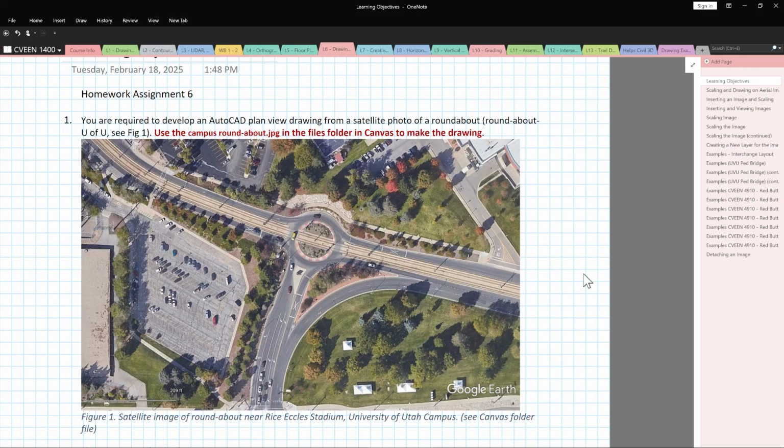The important thing to realize about these types of photos is they are called orthophotos, or orthographic photos, and what that means is the photo has been rectified so that it is perfectly flat. Normally when you would fly and take images with a satellite camera, the edges would be distorted, making it so that the distances would not be correct on top of the photo. But the Google images have been corrected to orthophotos, so we can use them to draw directly on and get approximate distances. So the layout we're going to do is of the transportation system.